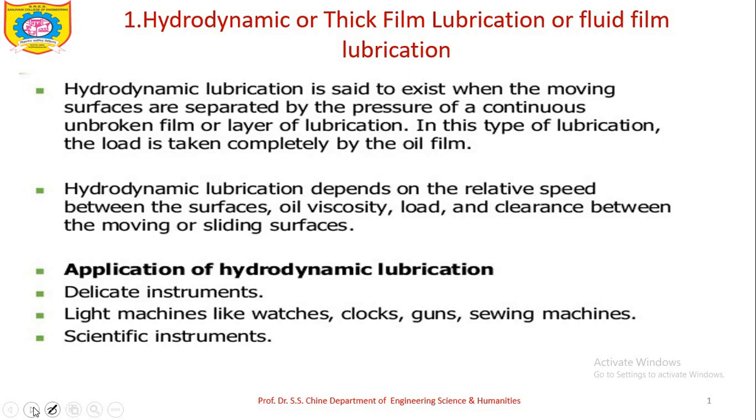So when to apply this hydrodynamic lubrication? If the moving surfaces are separated by the pressure of a continuous unbroken film or layer of lubricant, and the load is taken completely by the oil film. That's why we need to apply the lubricant oil as a thick film.